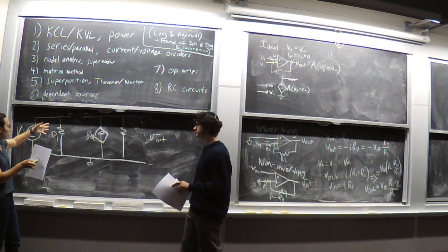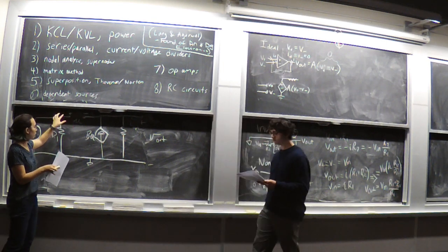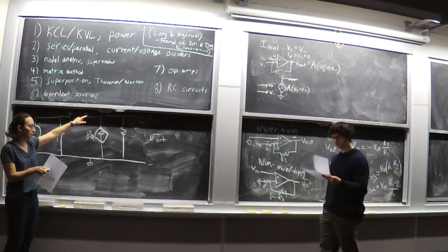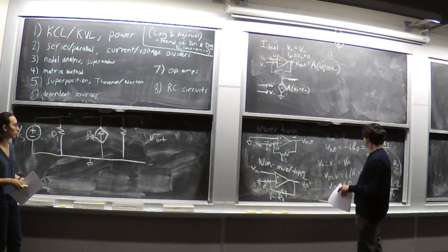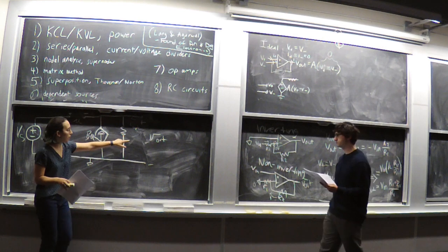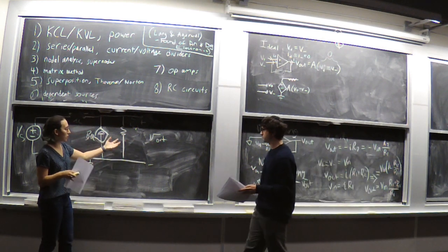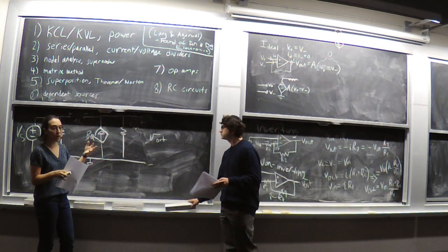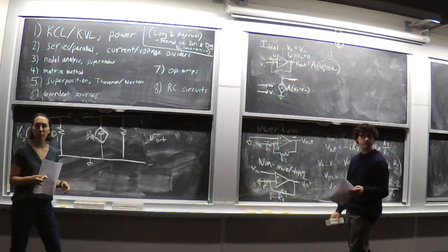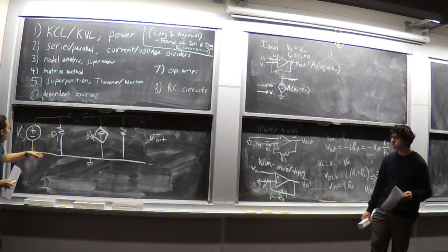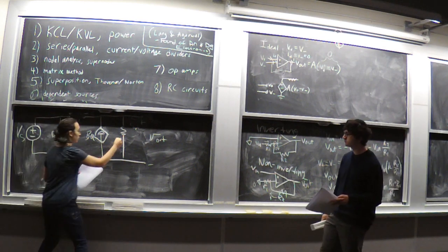Because when you turn on the circuit, there will be some voltage that appears between these two points, and that voltage is going to then feed into the voltage here. So U will not appear in your final answer. And when you find V out in terms of I out, what that's essentially doing is finding the Thevenin equivalent of this circuit. Is that second resistor equal to R1? This is R1, oh, R2, sorry.